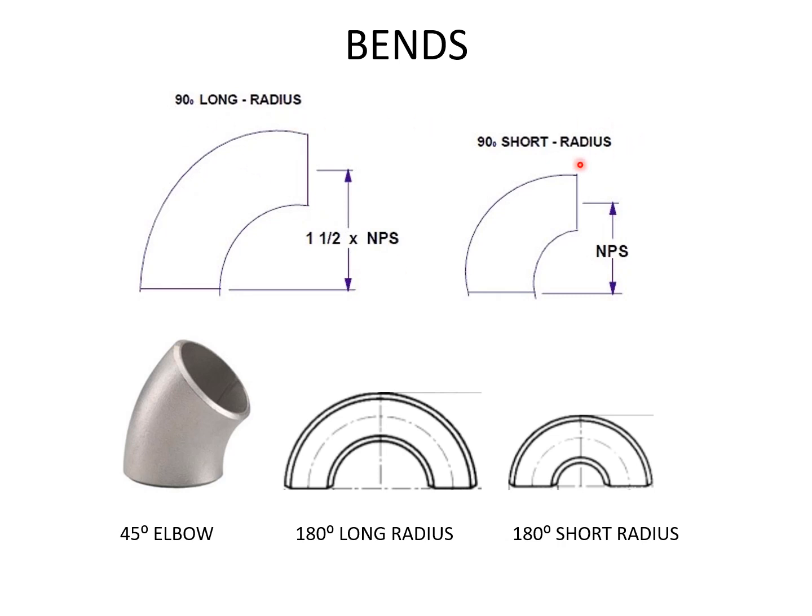And if there is no problem with the pressure drop, we use short radius elbow. This is a 45-degree elbow; where the pipe routing has a 45-degree bend, we'll use this elbow. And 180-degree long radius elbow: this kind of 180-degree elbow is normally used in coils.